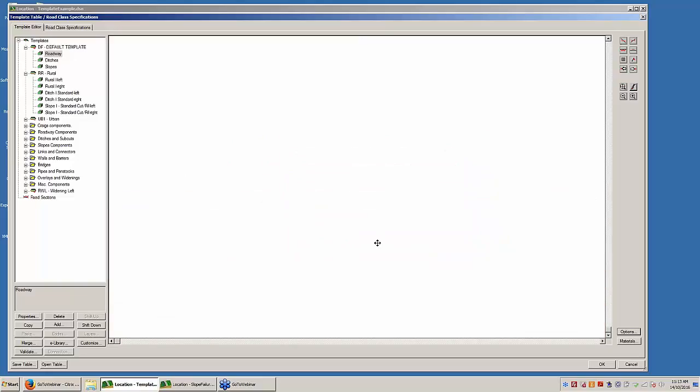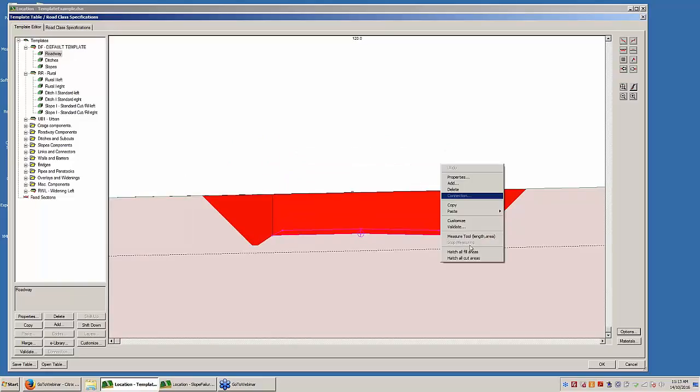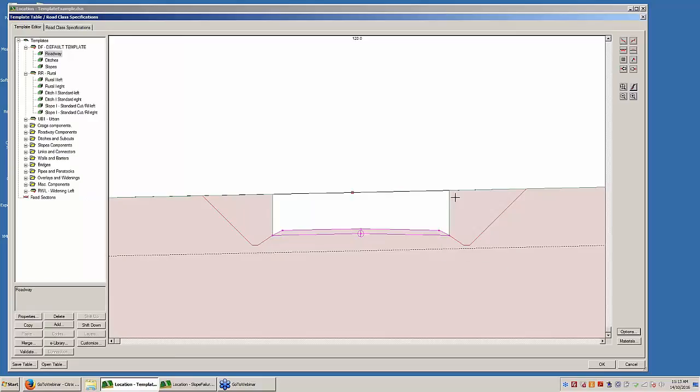And if it was in cut, well, let me turn the cut off here. There. You can see that it's cut out the roadway, and at this juncture in the processing, I've stopped it after the roadway, and that's what my merged surface looks like after the roadway.